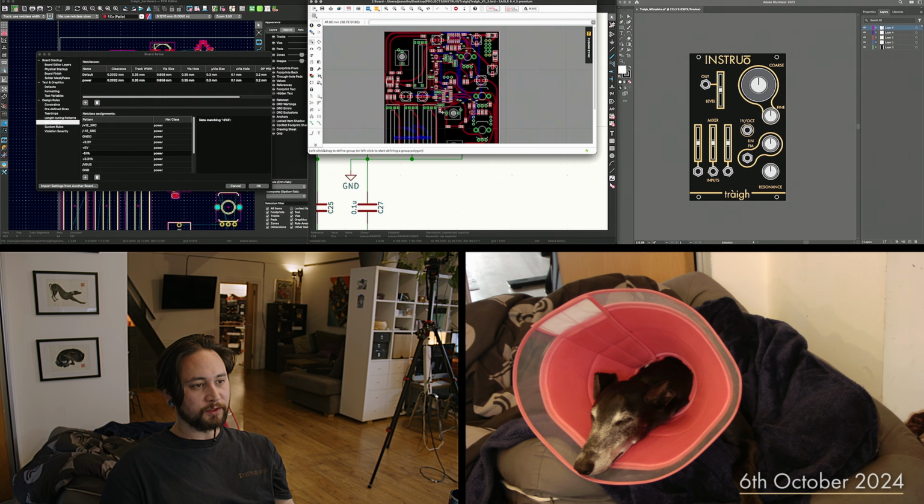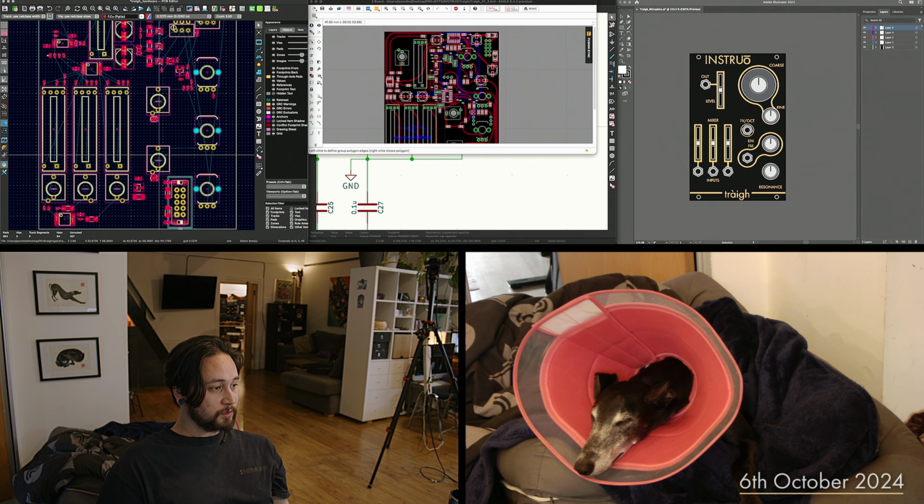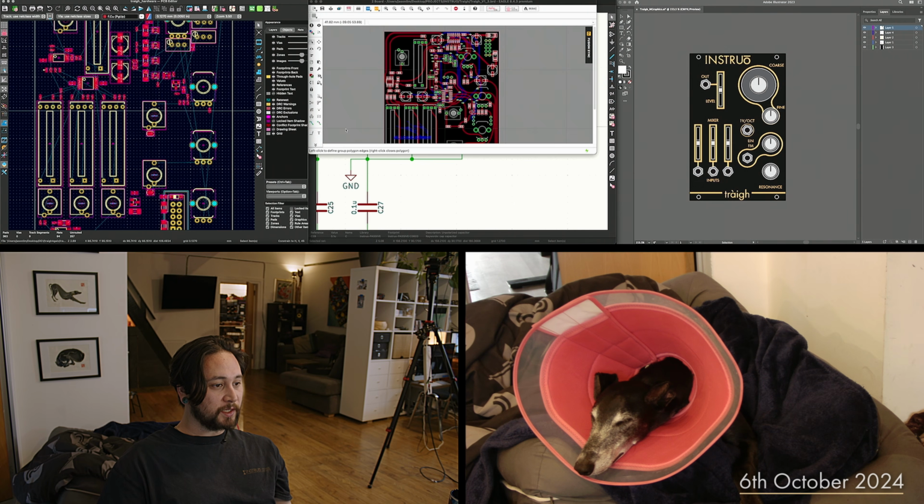Can't remember how that's defined in Eagle, but that should do it. That'll give me that clearance and that track width spacing. I don't think I need anything else. I'll probably manually override and draw thicker traces around here. And then when it comes to actually routing,